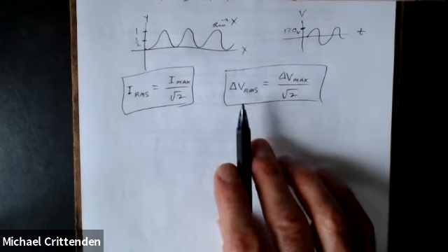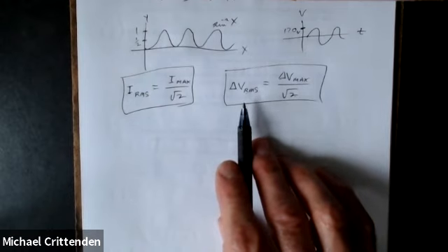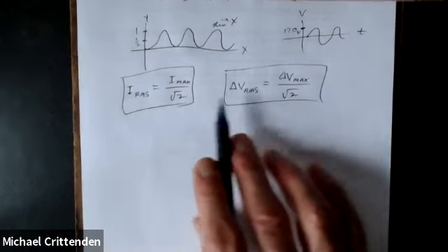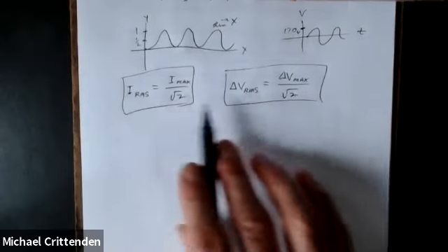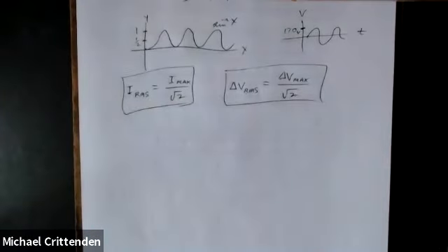If you get an AC meter, and you read AC amps or AC volts, that's RMS. So once you get away from some sort of highbrow course about this stuff and get out to where you're actually just fishing wires through walls or soldering something, it's always root mean squared that people talk about. They talk about the effective voltage and current.